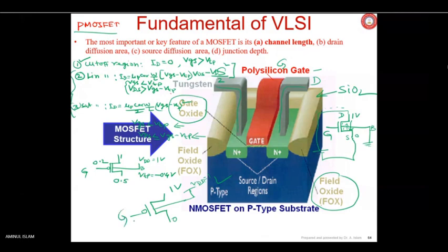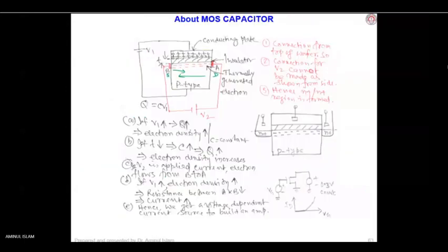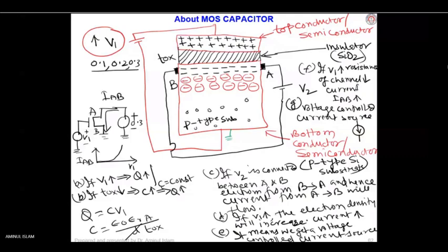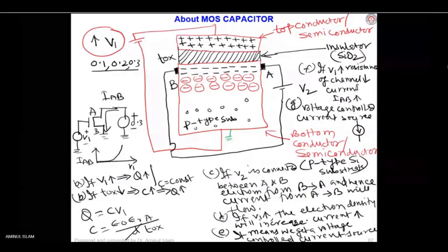Now this is the gate, obviously no problem. But out of these two terminals, which one is what? Can you tell which one is what? Again, I am telling you, think of the terminal which is sourcing the carrier, that is the source. The other one is the drain. What is the carrier in a PMOSFET? The current carrier. In the last lecture we have discussed it. Electrons is in case of NMOSFET.